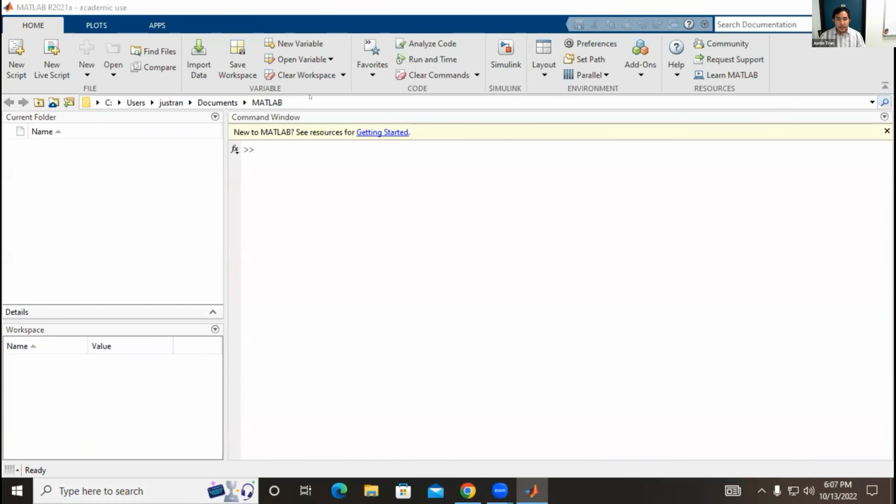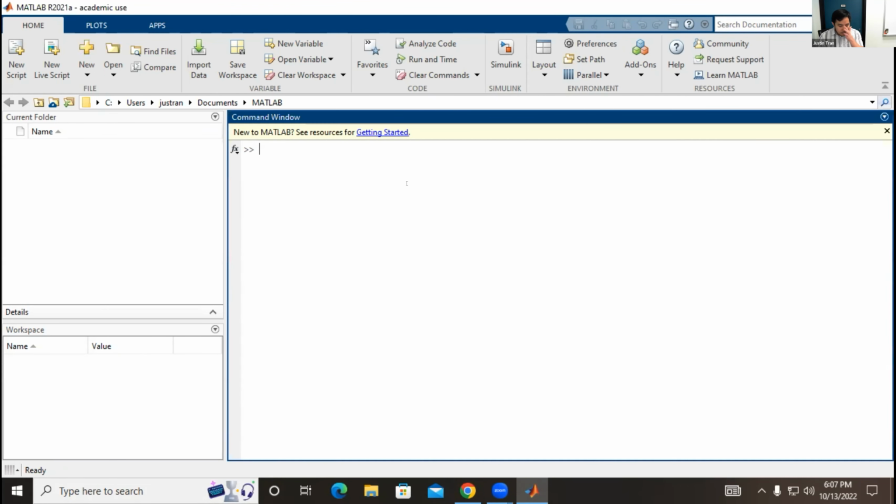You don't even have to use a script for this. You can do this all from the command window. First, you need to define 2 entries here. You write that as a comment. The first entry is going to be the square matrix that represents the stiffness matrix. And second, you're going to need to enter the forcing vector, which holds the boundary conditions.